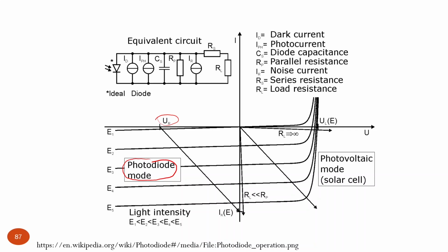So current voltage characteristics, how do they look? It's actually quite flat. You can see for different light intensities, it's just with very small slope, because the efficiency of photo-generated charge carrier collection increases slightly with reverse bias, but even at zero bias for good devices, we already collect most of the charge carriers.